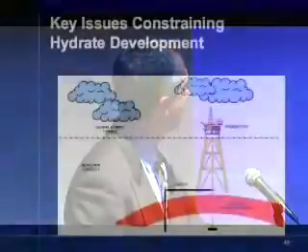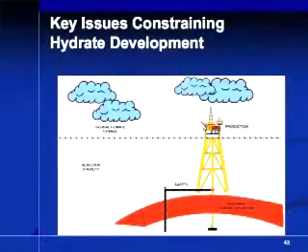You've got production problems, safety problems, resource characterization. So when you start producing it, it starts to dissociate, and then you get bubbles. Say if it's subsurface in the sea, you get bubbles that come up that expand rapidly. How do you capture these before you cause problems to your production platform or ship that you're drilling in? Seafloor stability. Are you going to have sloughing off your seafloor? It's going to cause instability. And then questions about global climate change, too, if you're releasing these things into the atmosphere from the ocean.